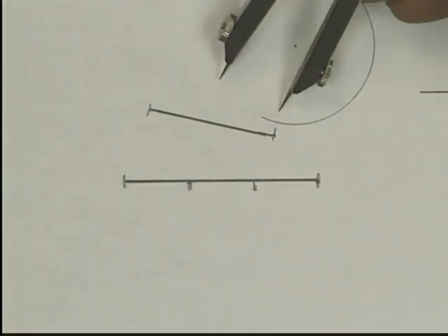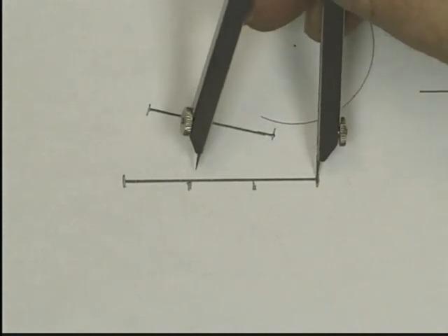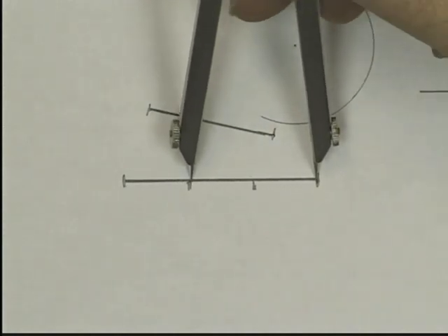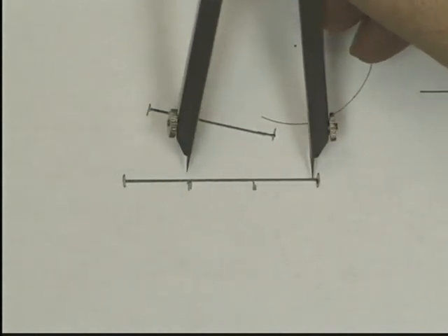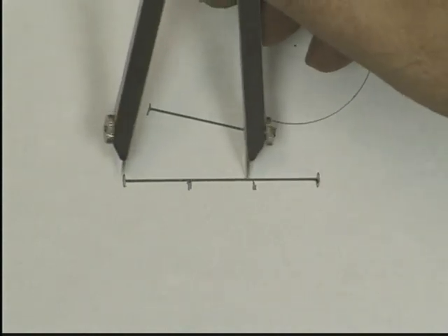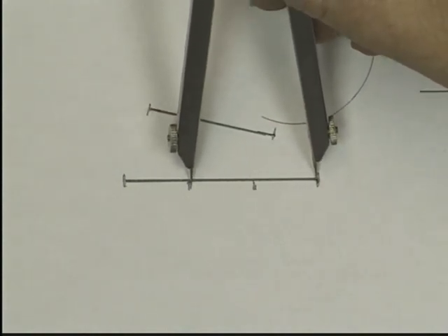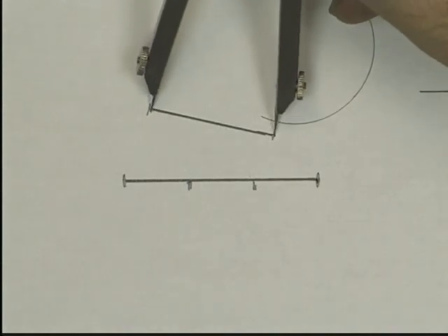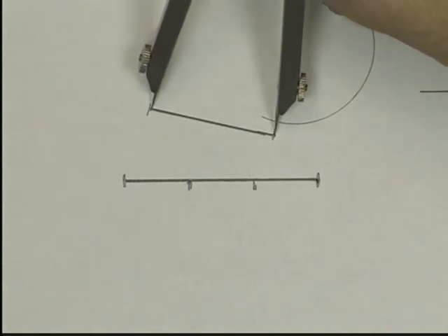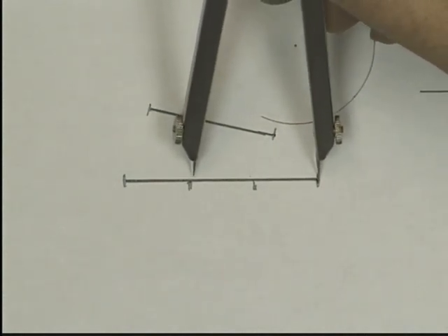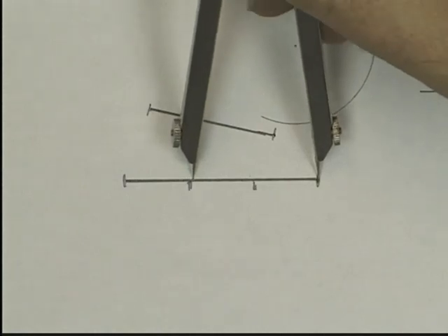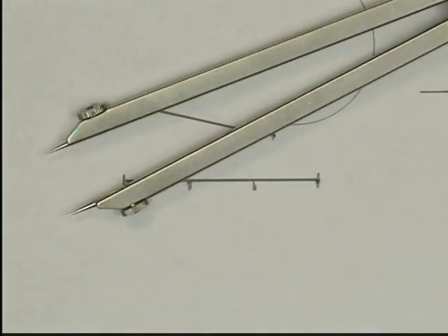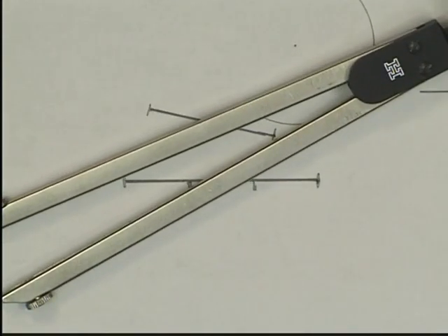So the illustration was that I wanted to transfer a particular distance to some other line. In this case, I wanted to transfer 2/3 of the length of this line. I don't know what it is, I didn't measure it, but I know exactly 2/3 because I used my dividers to figure it out. So I can set that on the 2/3 distance, and I can transfer that distance anyplace else. Now, if you get into an advanced class called descriptive geometry, there'll be lots of applications for transferring distances from one view to another view, and the dividers is a very handy tool to use for that. So dividers, double duty. Use it to divide lines, use it to transfer distances.